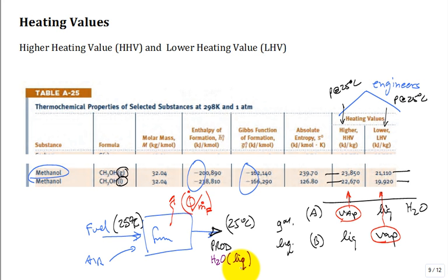But we said, look, we want the most heat out of our furnace, so let's cool the products to 25. How are you going to cool it? By pushing more heat out of the furnace. Q dot is increased by making this temperature as low as possible. The lowest reasonable is 25 degrees C. See how Q dot is increased? I get a maximum heating value if I say the products go out at 25 C.